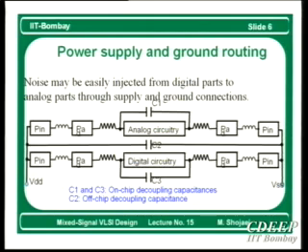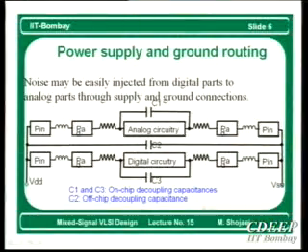For example, if you put a sine wave on VDD, you will see the same sine wave here without any phase shift, ideally, if C2 is very large. So this means that VDD and VSS are working together. In fact, the circuit won't observe this variation, because from the circuit's point of view, we are talking about relative potential, right?